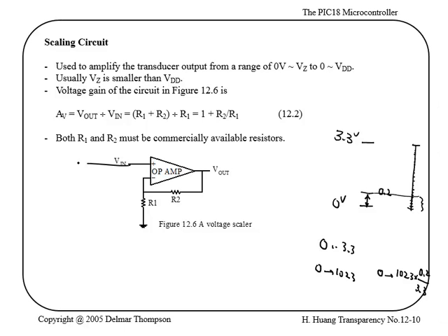So if this is coming from your sensor, through a conditioning circuit, and this is going to your PIC pin, and for now let's assume that your sensor goes from 0 volts to some other value. If the offset is something else, we'll have to deal with that later. But this is going to be one circuit that takes care of scaling the input signal to the output value.